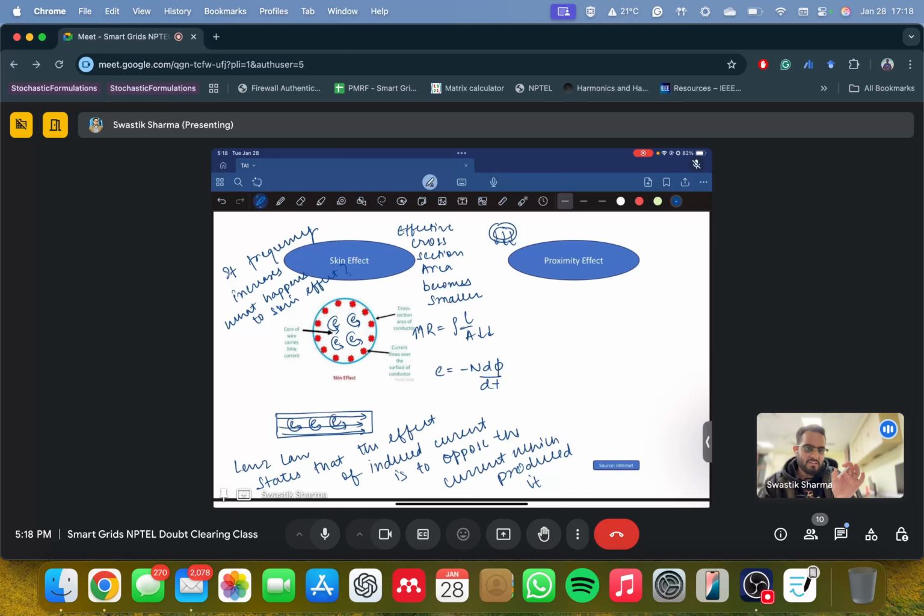When the pressure is low, water comes out of that small cross section. But now you increase the pressure, what will happen? The water comes out covering the whole cross section of the pipe, very fast. That is what happens with frequency as well. When you increase the frequency of alternating current, the skin effect also increases.